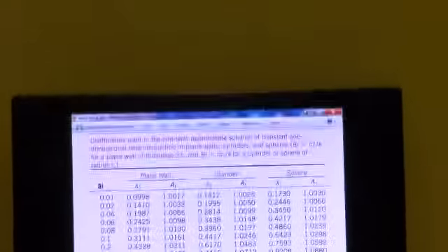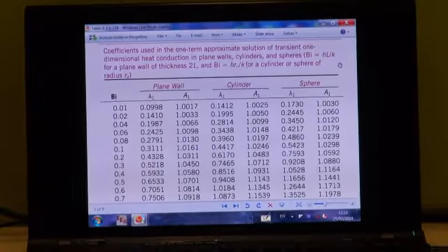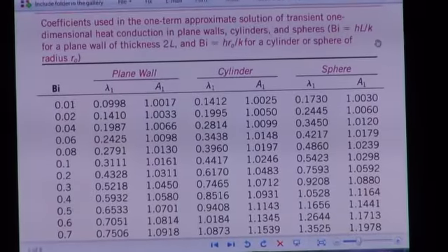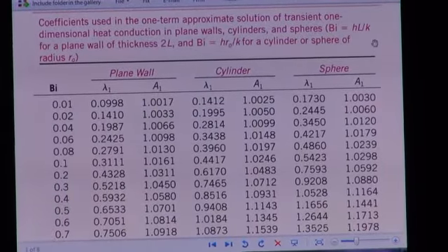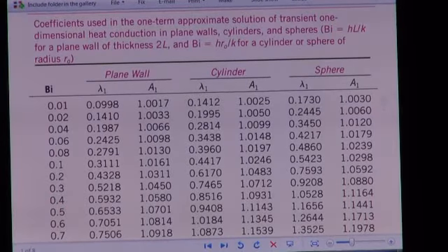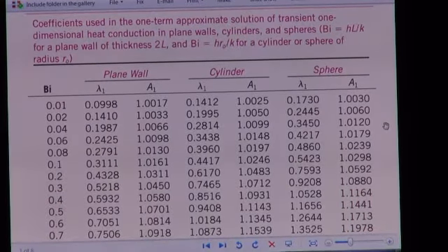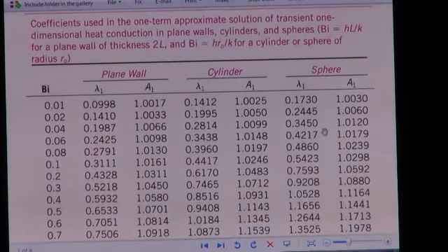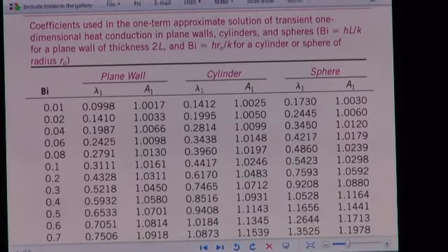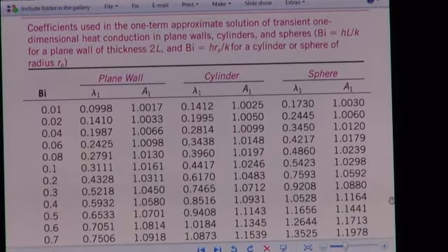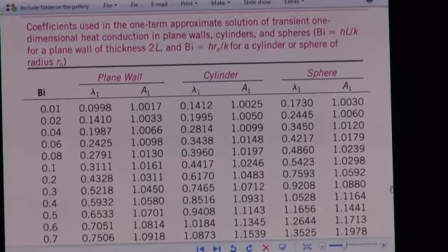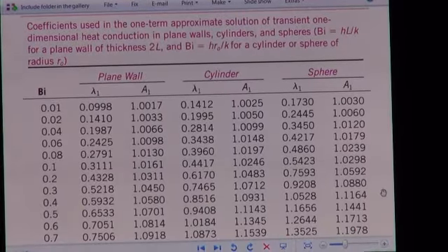Won't your number change when the formula is hR? Good. Great. That is one of the traps I've pointed out previously for you. That Biot number, remember, has been calculated for the plane wall. So you cannot now use it for the long cylinder.